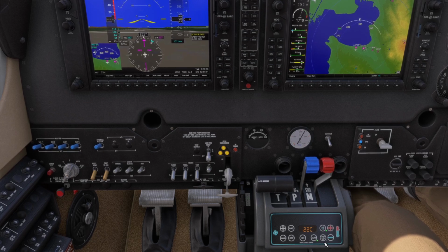Here we have the windshield defrost. Now, from this lever here, when we have installed the climate system, the windshield defogging is controlled by the system. To have the system provide warm air, as the windshield defogging, actually it's defogging, not de-icing or defrosting, is provided by heated air that hits the windshield.